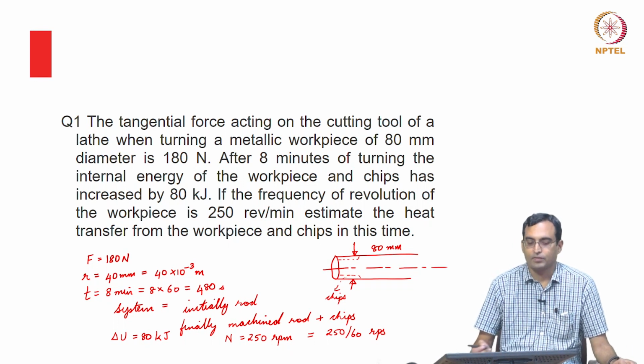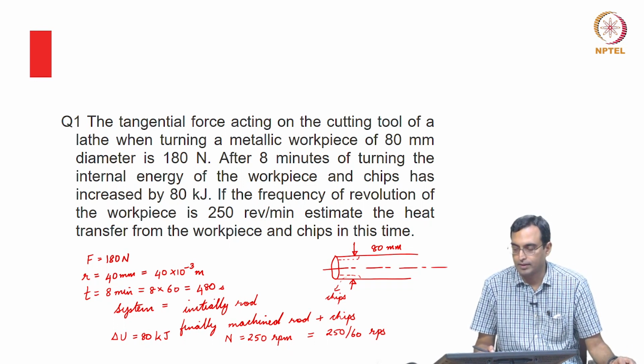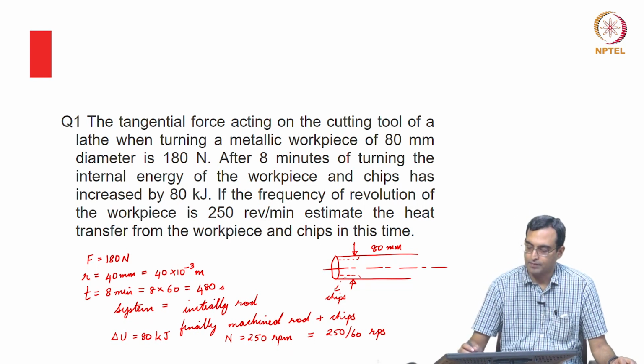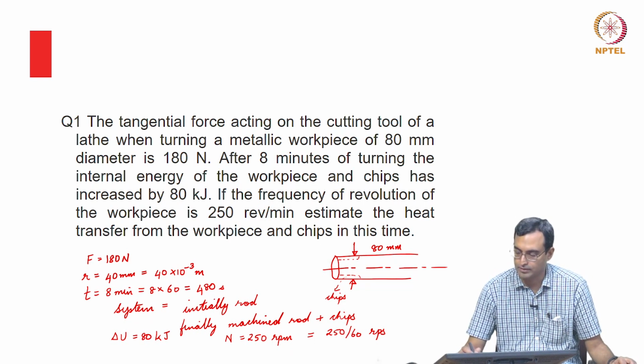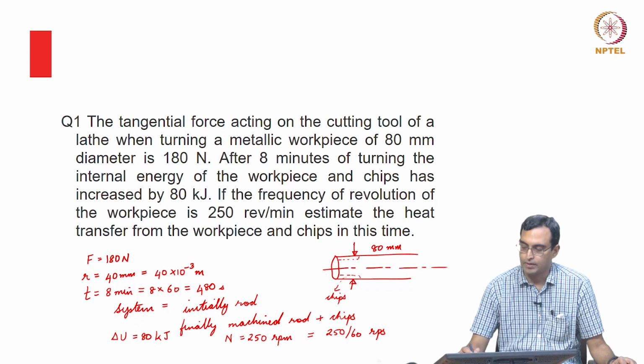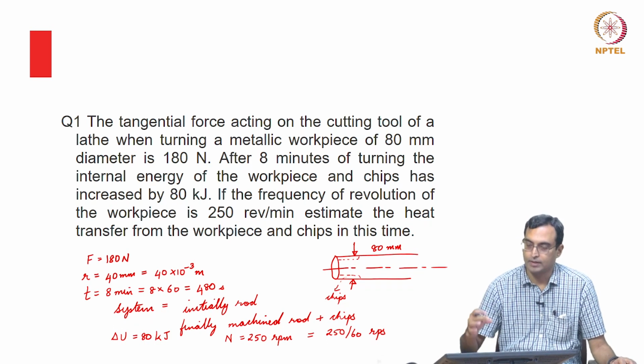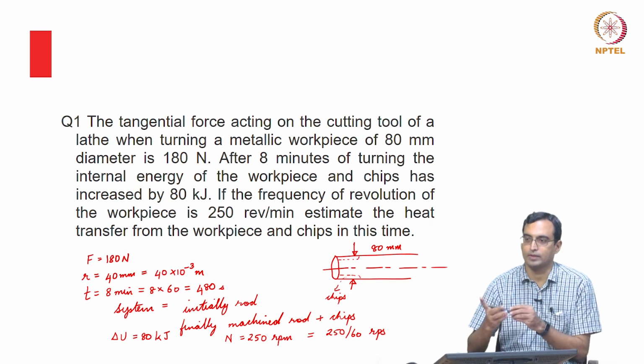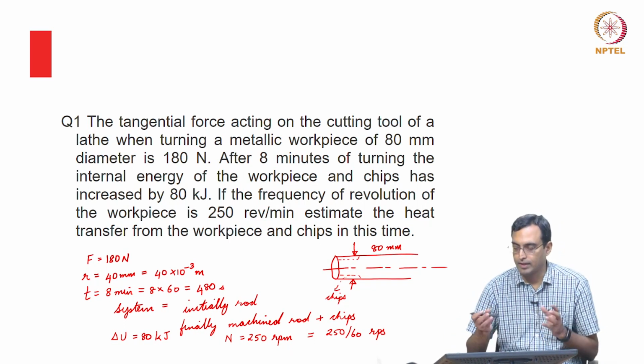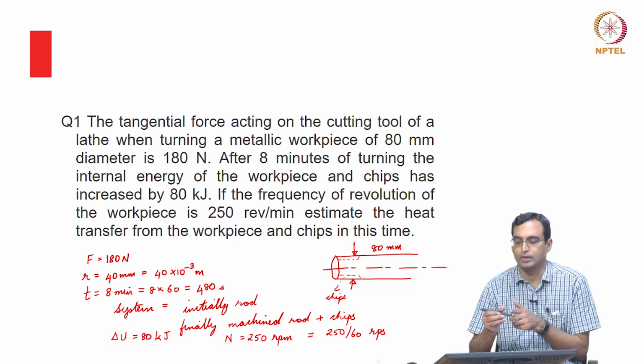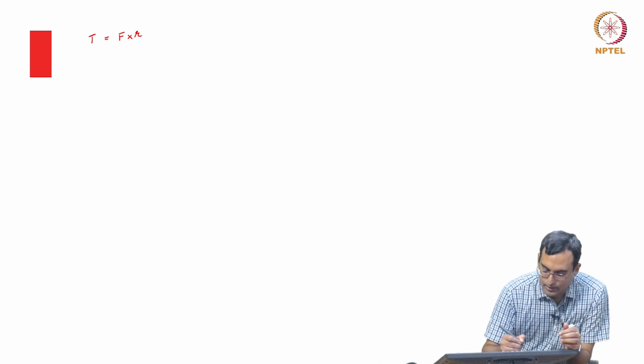So because we know the force is acting, we can calculate the work interaction for this. I have a force which is acting tangential, at some distance from the center, and this whole rod is in rotary motion. So I can calculate the cutting torque which is acting on this. The cutting torque would be given as the force into the distance from the axis, which is some r.